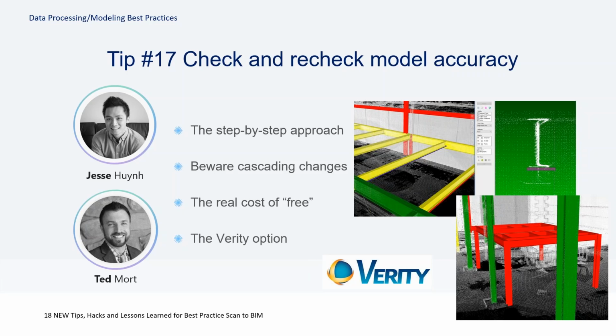So one of the things that I like to do is take a slight section of the floor plan at the very bottom and look from maybe plan east all the way to the west and see if there's anything wrong with it, and catch all of those issues and proceed to move the sliver up another several feet and do the same process over and over again. Same thing for cross sections, so that you can catch whether or not maybe a floor deflection matches the scans throughout the entire space. And you won't necessarily know that unless you're able to approach it methodically in a logical way.